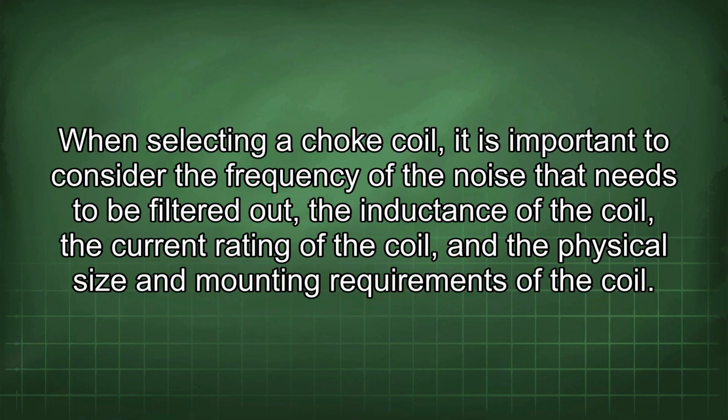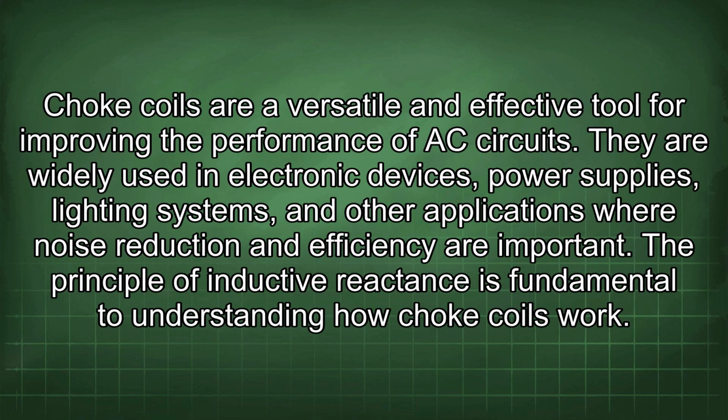When selecting a choke coil, it is important to consider the frequency of the noise that needs to be filtered out, the inductance of the coil, the current rating of the coil, and the physical size and mounting requirements of the coil. Choke coils are a versatile and effective tool for improving the performance of AC circuits.